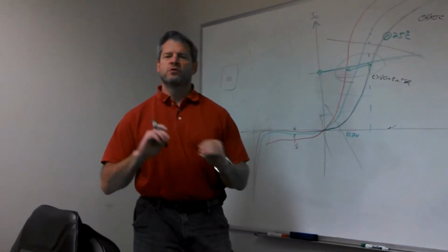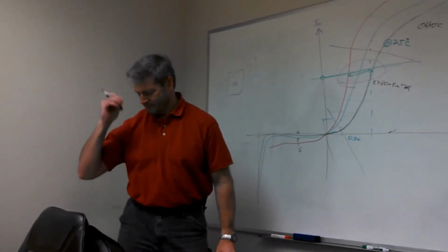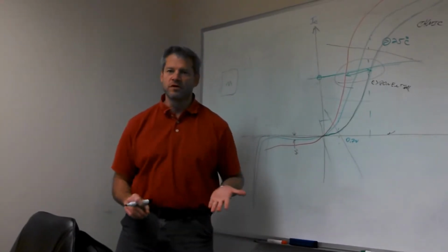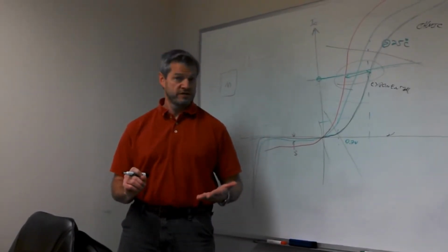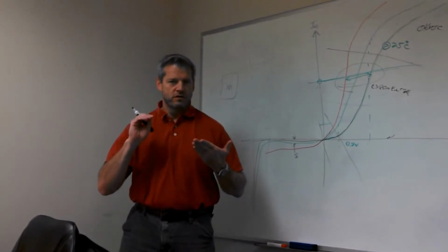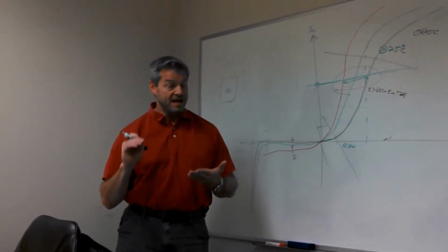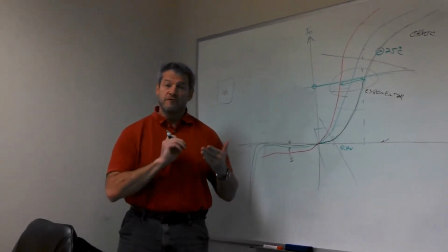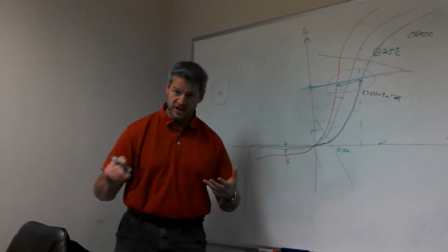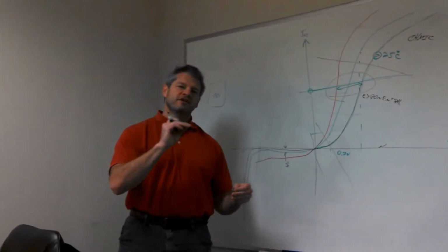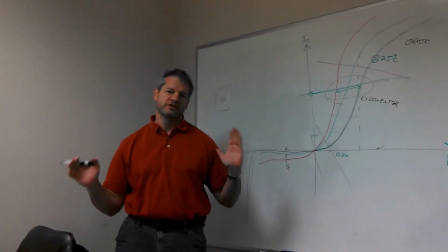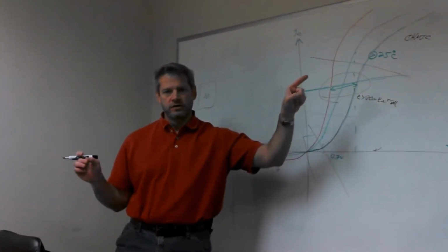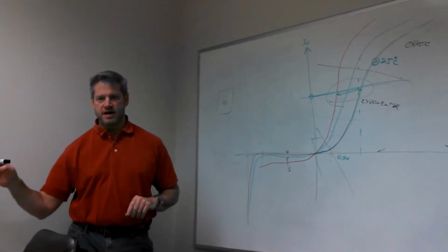So when we go through our electronics classes and we design a board, we're making an assumption of what the temperature is. It's a pain, but for a good design, you have to design your circuit, and then look at what your expected temperature ranges are going to be, and ask: does the circuit behave the same way at cold, and at hot?